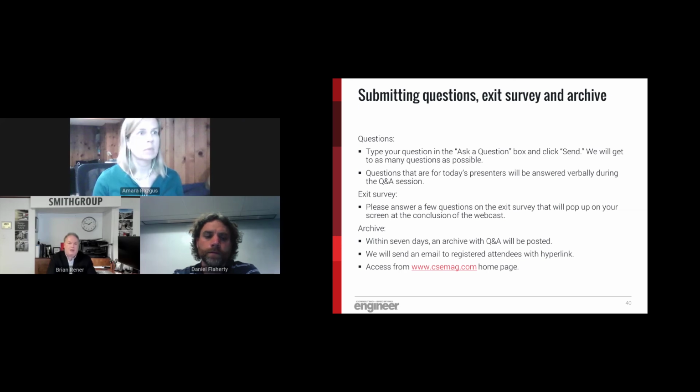Really, if you look at what was behind the NEC addition in Article 700 about the temporary hookup box, particularly on a single generator that's providing your emergency power, that generator can fail. It can need repairs. It can need significant maintenance. There's any number of reasons why that generator might be offline. The owner may wish to perform some maintenance on it that it knows it needs to do. And the fire pump is an emergency required load. You cannot leave the facility generally unprotected.